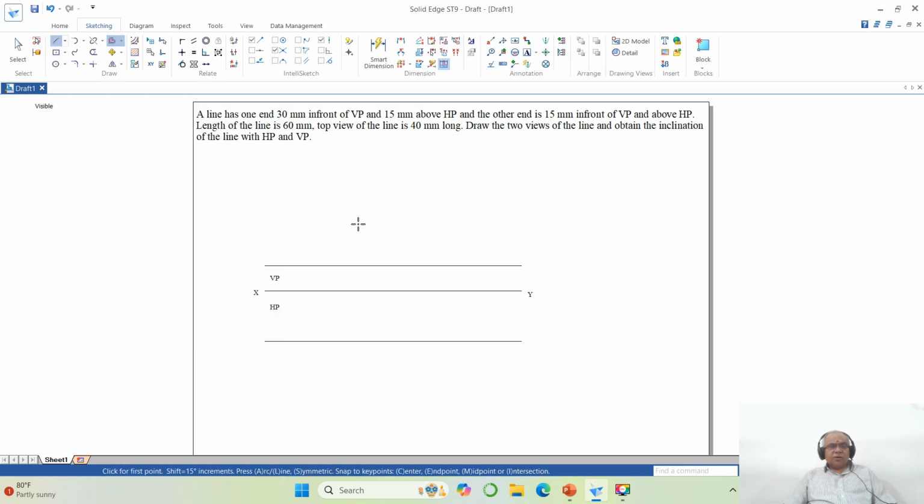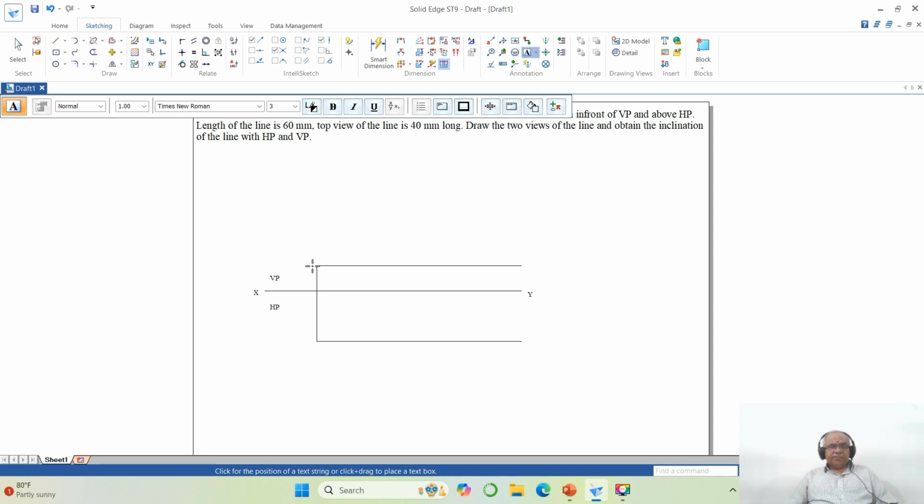Now I want to draw one vertical projector so that I will get the points A and A dash. Trim the corner between these two. Now I need to mention those points here. So I will say A dash here and I will mark this point as A, and of course you have capital A in this, and here also you will have capital A.